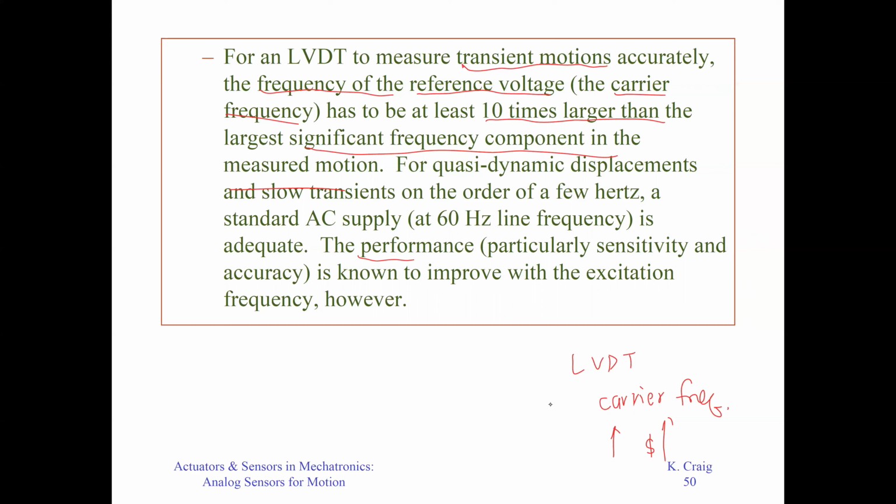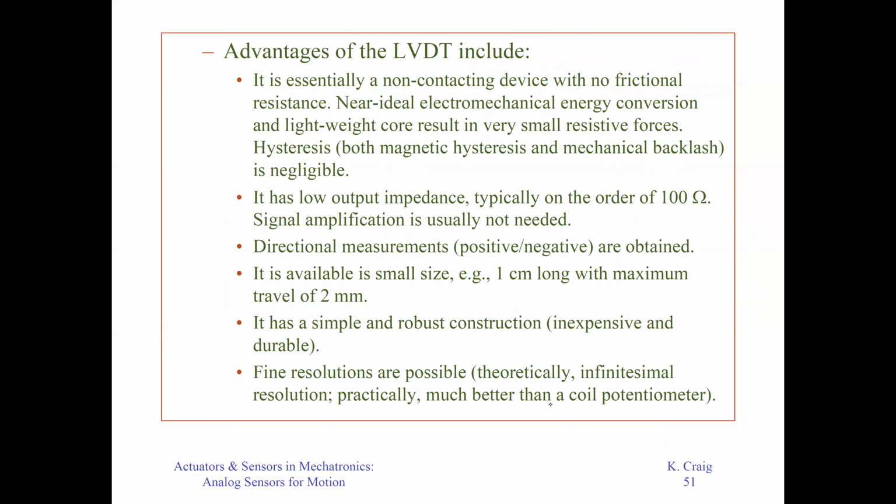So the performance of the LVDT is sensitive, and sensitivity and accuracy will improve if you have a higher excitation frequency. Okay. So advantages, you should know that. Let's go through that. First of all, the motion and the device is non-contact. And the hysteresis is negligible.